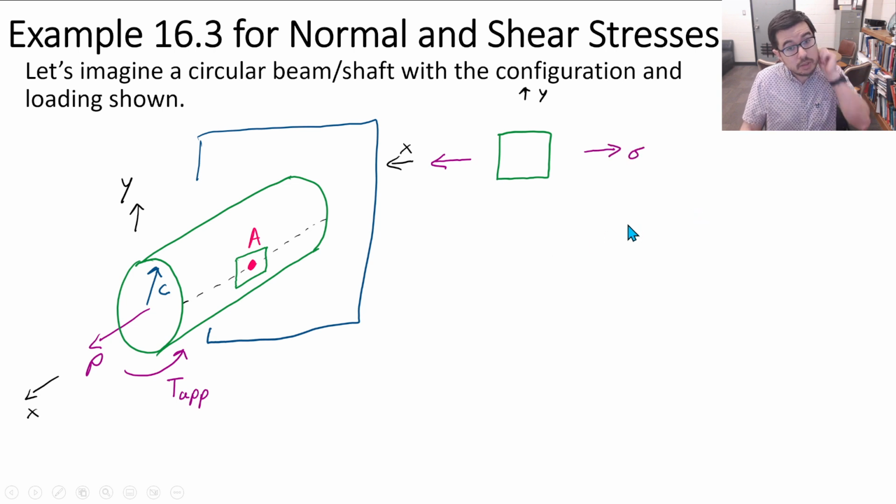And now let's draw our tau xy. Again, we need to use a little mental visualization, but like we said, this side's going to be going up, right? So which direction on the left side of this element should it go? Well, it's going to go up, right? Just like that. And in order to keep ourselves in equilibrium, we're going to draw another one that meets it in this corner. And then I did it correctly this time. We have opposing arrows meeting the bottom right corner.